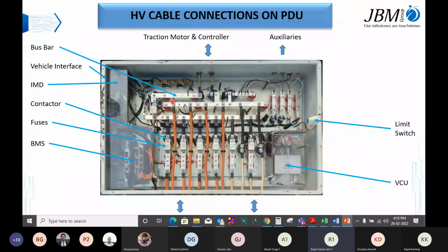No, all battery strings are connected to the common bus bar, the lower one. The positive one is the lower, longer longitudinal bus bar we are seeing, and the negative connections of all the strings are connected to the negative bus bar. These two bus bars are the common point for all types of load. All battery strings supply power to these two bus bars, and all other loads take power from them. So whenever charging occurs, the current will flow from this point also.